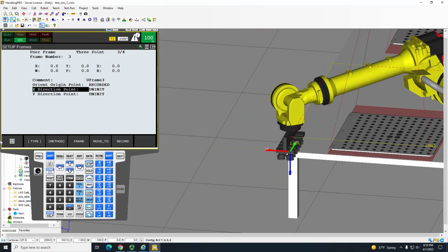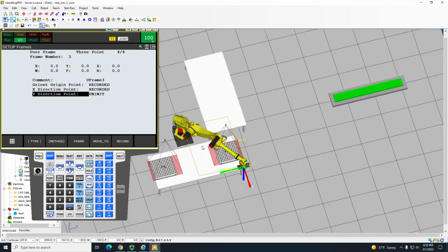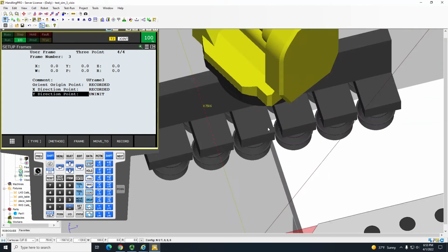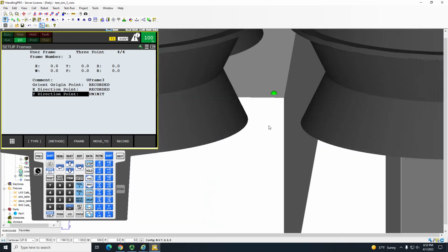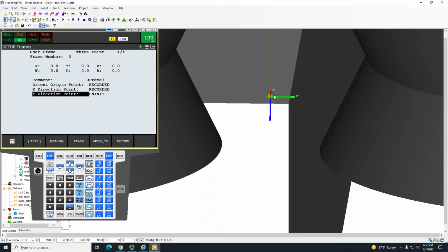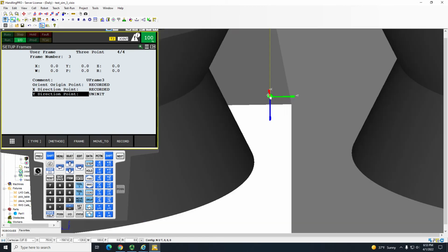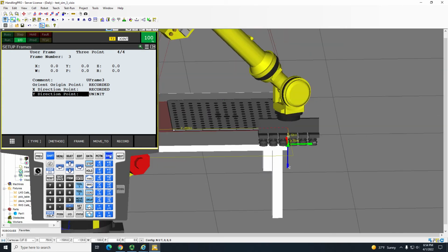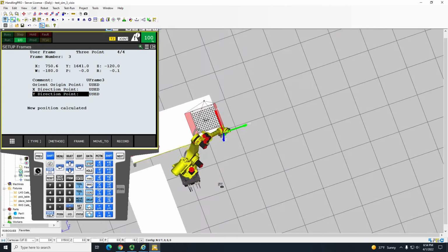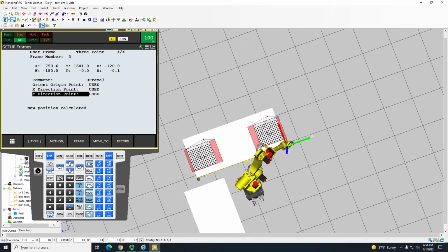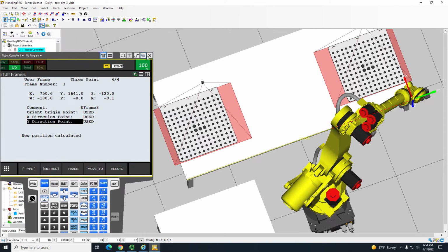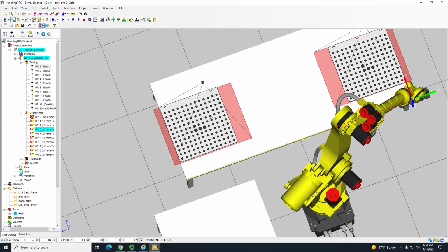I'm not going to cover the entire table for this, so I'm going to hit Shift, record, and go to the Y direction now. Y is going to be at this corner. Control Shift, hit on this point. Move my robot slowly here. Alright, it's not moving here again. Oh, it does move there. Okay, Shift, record. This is my user frame 3. Good. Orient origin, Y and X saved perfectly. Alright, this is done. Close my program now.